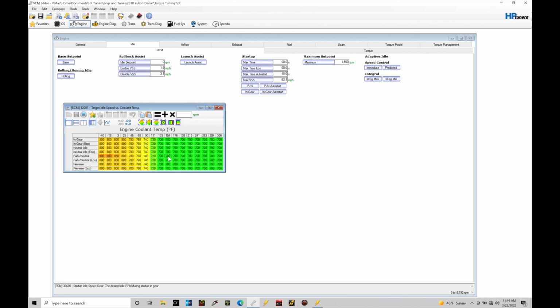We might be overshooting, we might be undershooting. And how the engine control module is going to deal with the over or undershoot is going to be different, but we'll find ultimately what it's going to do is try to regulate what the torque output of the engine is going to be to hit the desired idle speed. And that's what we're doing for idle control in any other application.